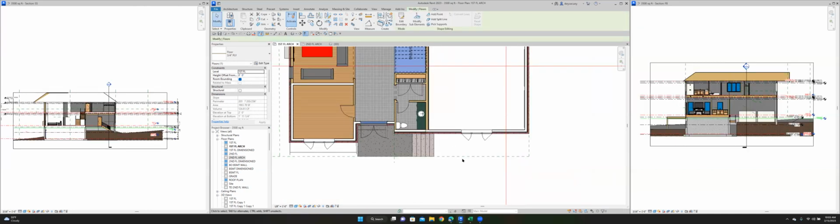So going to annotate. No, I just click right here. I should get my lines. Here we go. This one I already have. I'm just trying to think, this subfloor to come down to here, because this wall stays out. Not worry about where I put that one, because I'll use the trim extend, or still call it from the AutoCAD days. Just align those two. Look good. There's my subfloor.